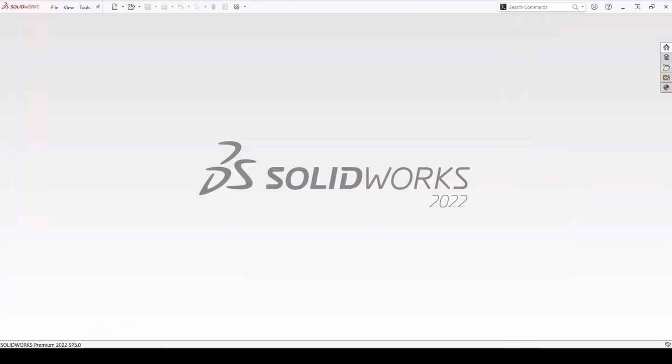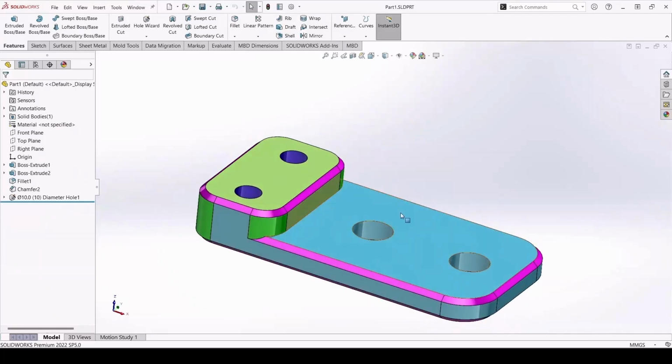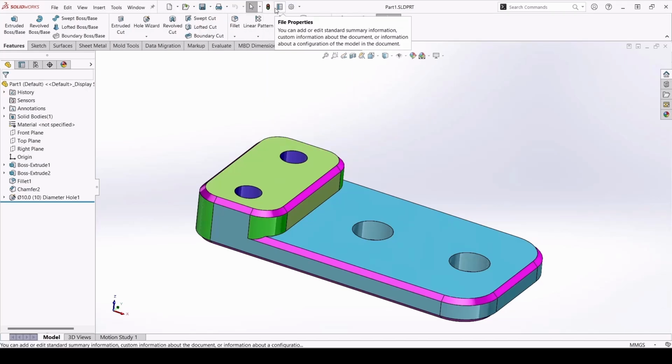As we said previously, in SolidWorks, we have many bars and panes that we will be using during our design. So let's just open up a file. That's the very first part that we'll be creating, but we will use it also just to tell you what each pane does. On the top here is your standard toolbar. What the standard toolbar does is allow you to create a new part, drawing, or assembly, and then save or print or update your file. We will be diving into updating and file properties and, of course, options later on.